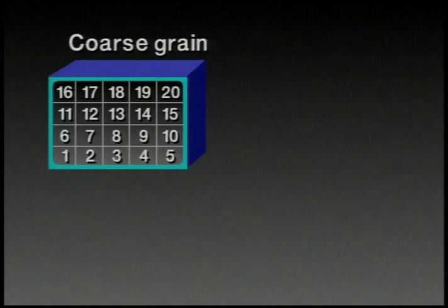Before we talk about whether we use SIMD or MIMD parallelism in the pixel area, we have to talk about the general partitioning of the frame buffer, how the memory of the frame buffer is mapped to the processors of the frame buffer, whether they have a single sequencer or separate sequencers. There's basically 2 obvious ways to go here. One is to just break the screen up into large coarse tiles and assign one processor to each one of these tiles. It's typically done in systems where there are fewer processors than there are tiles. As a result, in order to render a scene completely, all of the primitives that describe the scene have to be passed through the system multiple times, either by the application program or more typically by being accumulated somewhere in the graphics system and then passed through multiple times. Straightforward thing to do, but it has a very bad effect on context switching, which we haven't gotten to yet, but you can imagine that just dealing with that bulk of data, all of the primitives that describe a scene as part of the context of the machine, is a significant problem.